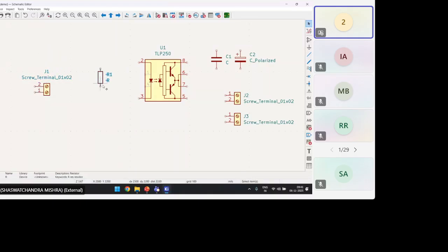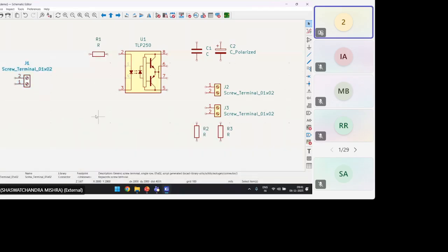So click on it, press R in order to rotate it. I will be placing it here. I have to rotate it in the direction like this. Either you can go here and click on this draw wires option, start drawing wires, or you can simply bring your cursor near this end and you will see the pen symbol appear on our cursor.